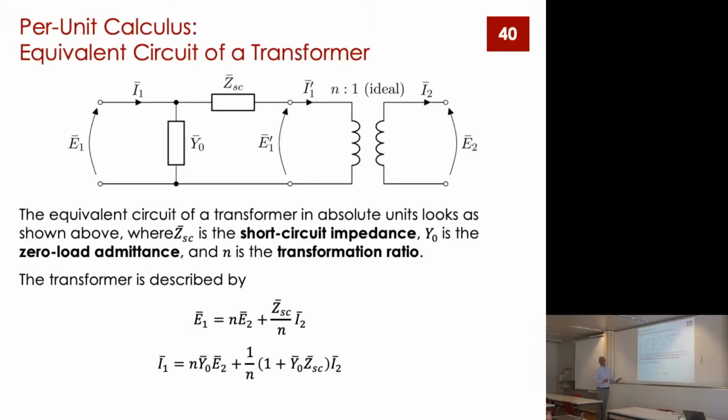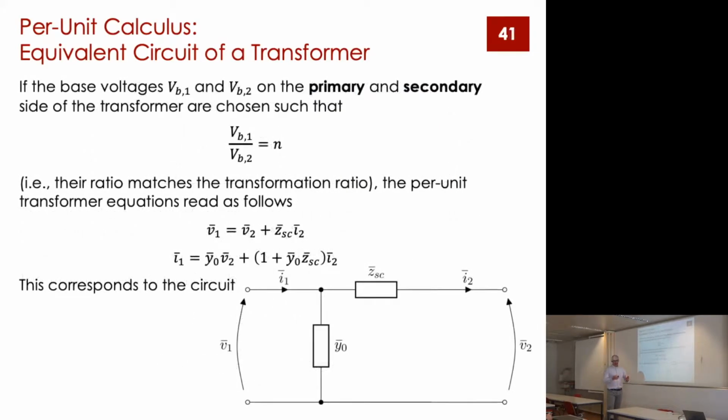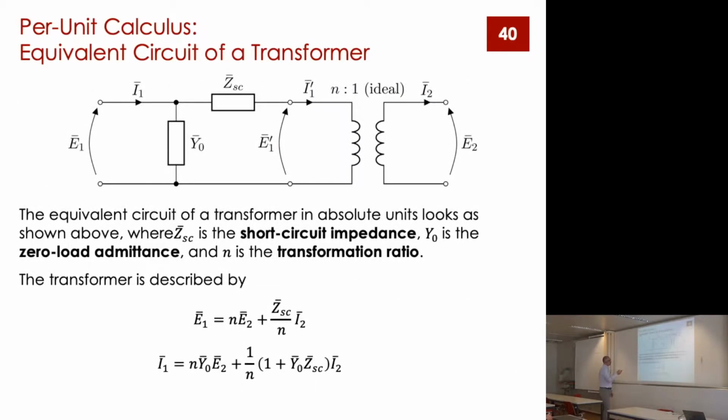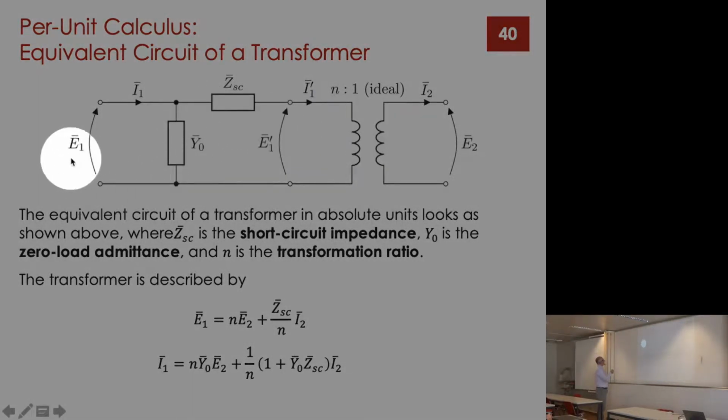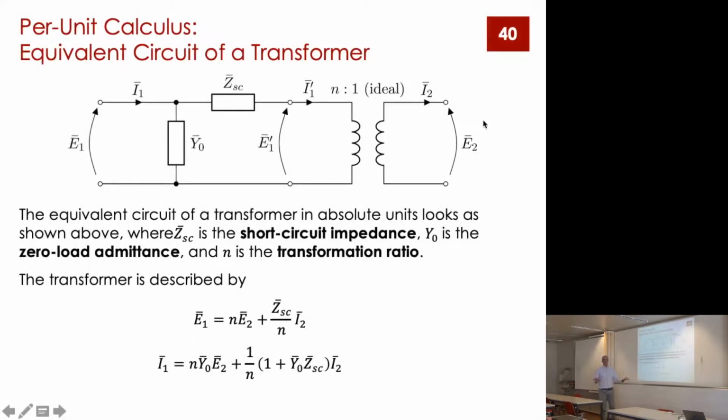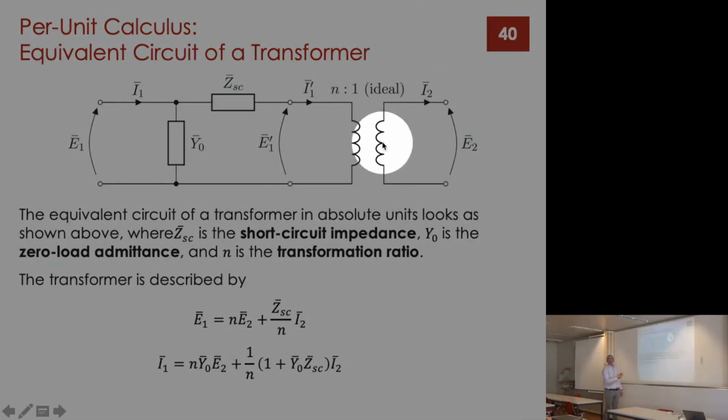Essentially, a transformer is a machine, this is for the non-EE people, which transforms the parameters of the power. It's a two-port system, like a line. The only difference is that at one port you have voltage E1 and current I1, and at the other port you have voltage E2 and current I2. The transformer can manipulate E1 and E2 by orders of magnitude using a magnetic coupling done by windings.